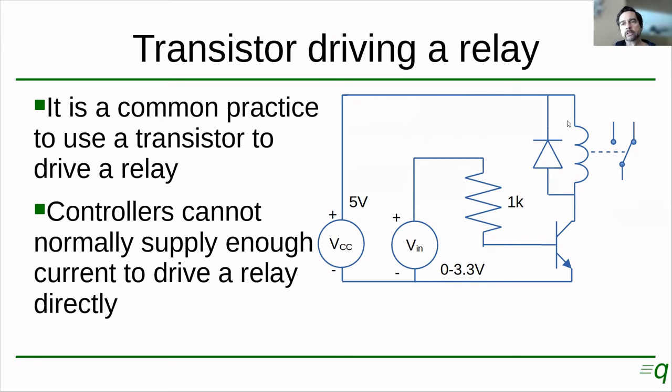And the coil is going to try to keep pushing the 100 milliamps through it, right? Because it's an inductor. And those 100 milliamps are going to be going through a much higher equivalent resistance here. That's going to cause the voltage at this point to shoot up, right?